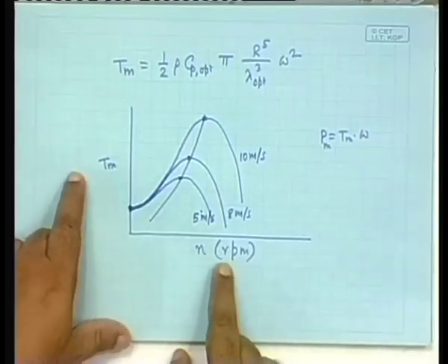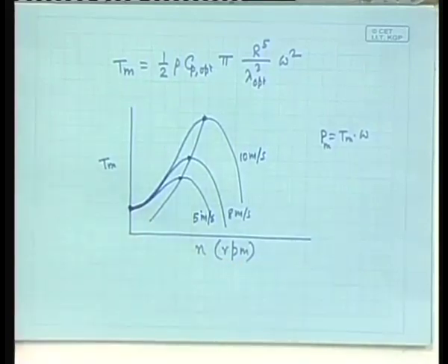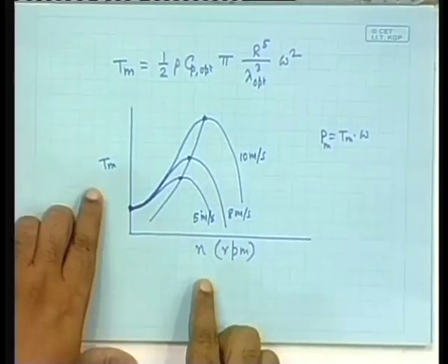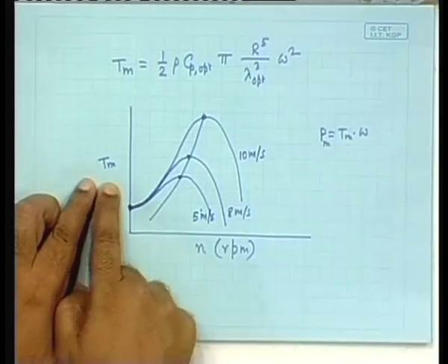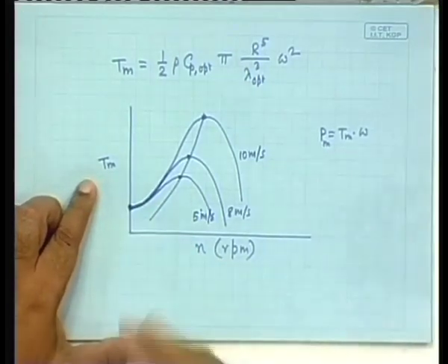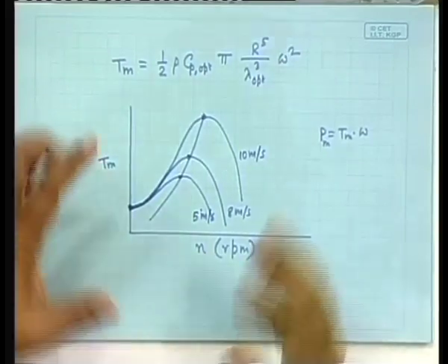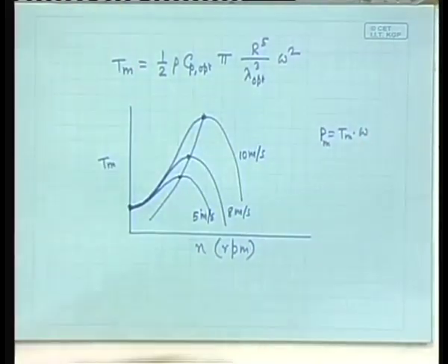Now, why do we need to understand this? Because this is the aerodynamic torque produced. That means the wind is producing this torque, but when it rotates, when you are extracting power from it, there is a back torque, right. When you are extracting power by converting to electrical energy, that conversion gives a back torque to it. So, ultimately when the forward torque and the back torque are the same, then that will be the equilibrium condition.